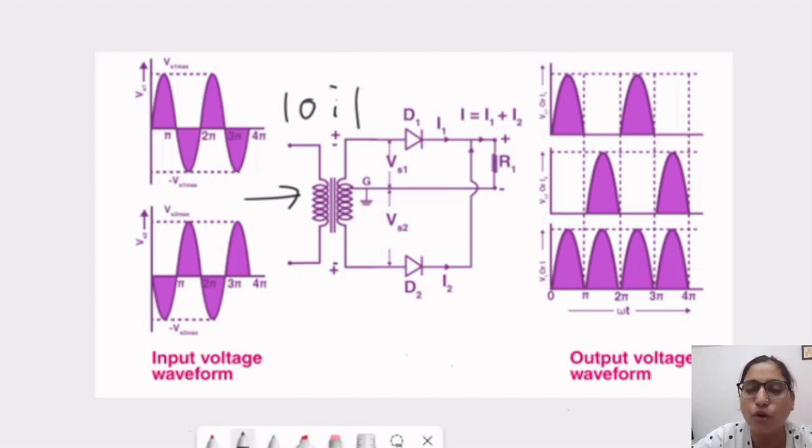If I am giving 10 volt to the input, it is becoming 1 volt at the output of the secondary coil. Let's say in India we have 220 volts of AC signal. Now it will become 22 volt at the secondary. Why so? Because this is the process of a step down transformer. Now for the diode circuitry we will get the lower voltage.